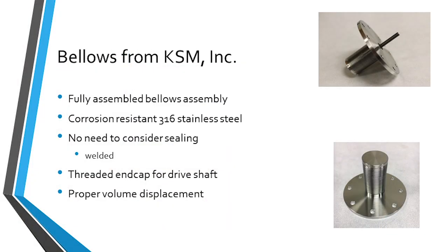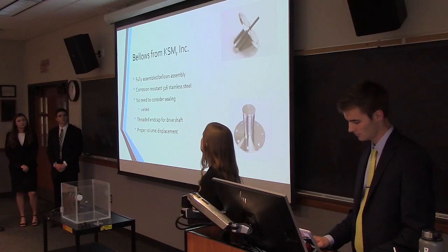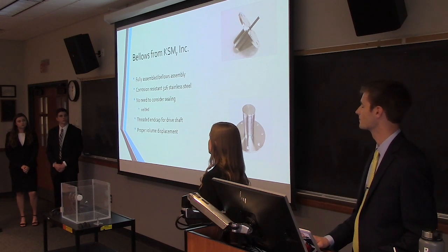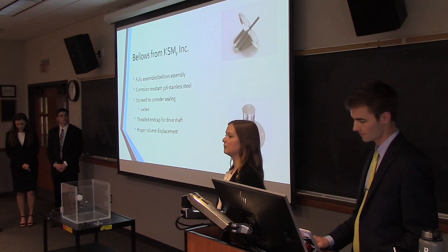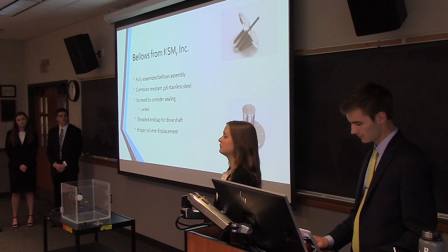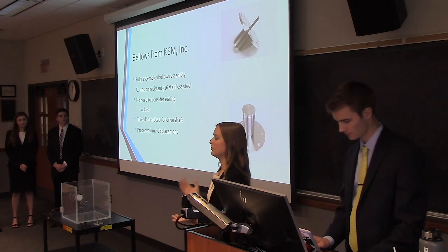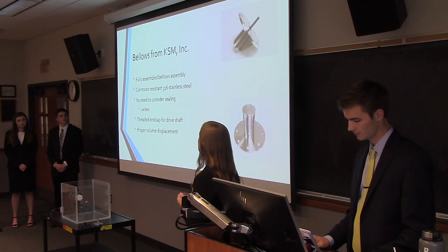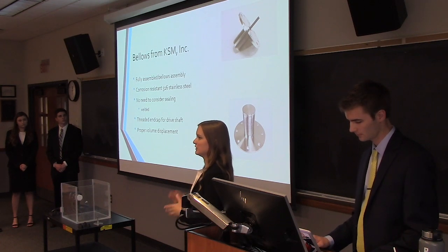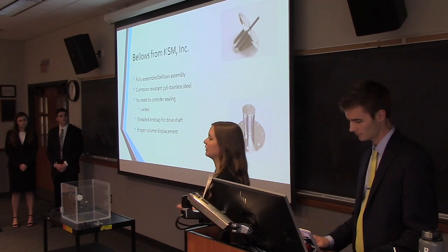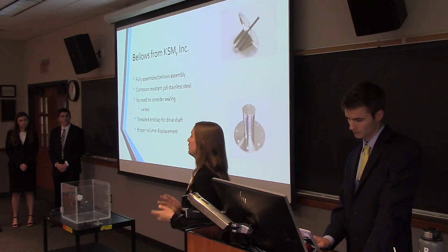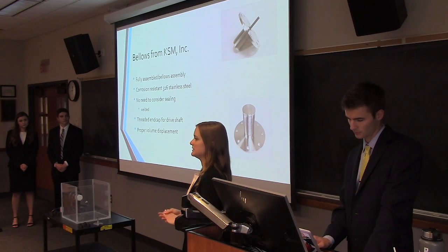They are bellows from KSM, which is also a bellows manufacturing company. The benefit to choosing this design was that it is a fully assembled bellows assembly. So they were able to supply us with 10 fully designed bellows assemblies that we are able to just apply to the tank and see how they work. They are made of corrosion resistant 3/16 stainless steel, which works well with the seawater that we're using. And since they are fully assembled, they are welded properly, so we don't need to consider any sealing issues that we might run into.